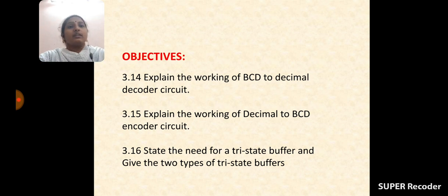So in multiplexer, to select the input lines, two more additional lines are used. These lines are called selection lines. Okay, according to the formula 2 to the power of n is equal to 4. So here 2 to the power of n is equal to the number of input lines. So n is equal to the number of selecting lines.